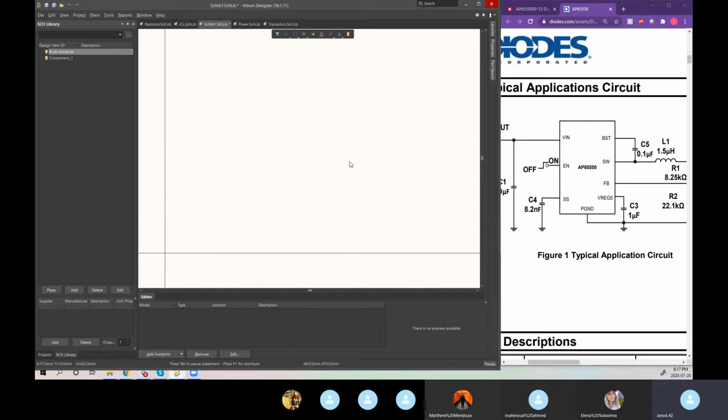So if you're making components for Phantom, or in general, if you're making new schematics, new libraries, you want to make sure that you're always keeping your units the same. So don't create a couple components imperial, a couple components metric. It'll just cause misalignment issues.